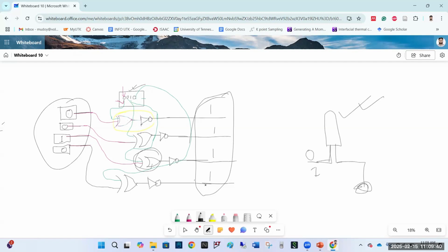So analyzing these 4 results, we need to turn this LED on. So how should we connect these 4 to this LED? What do you think? When should this LED turn on? When all these 4 XNOR outputs are 1, right? Then it should be turned on. If there is a 0 right here, then the LED should not turn on, right? So how can we do that?